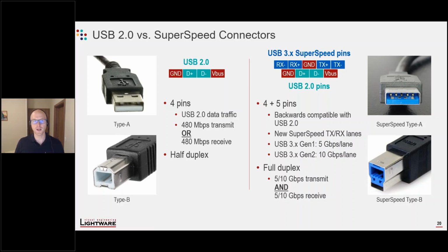The maximum data rate on this wire pair was 480 megabits per second, but it's a half duplex standard. So this connector or cable can only transmit or receive at any given time. It cannot transmit and receive simultaneously. So it works like a walkie-talkie.